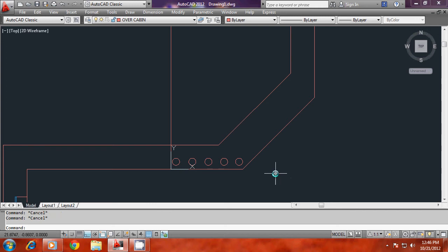In order to get that, the ideal thing is to rotate the UCS about the Z axis through 45 degrees, so that your X will get aligned in this direction. So I'll go to UCS and I'll go to Z axis and I'll give an angle of 45 degrees. So UCS is rotated through an angle of 45 degrees. So X is aligned at 45 degrees.